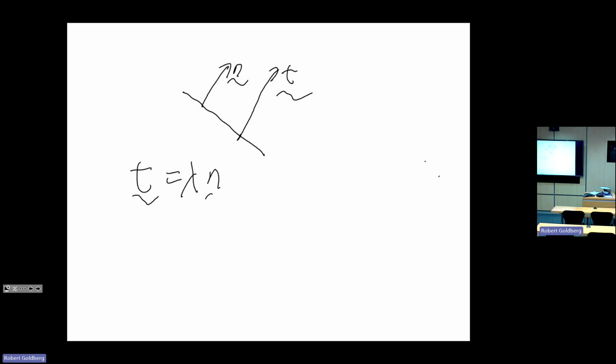So from a cartoon sense, we have some plane with a unit normal vector n, and we've defined the angle of this plane so that the stress vector is parallel to the normal vector and perpendicular to the plane. So we can say that our stress vector is just equal to some scalar lambda multiplied by the normal vector.